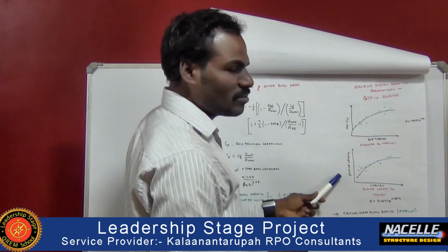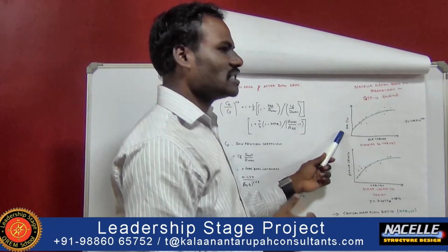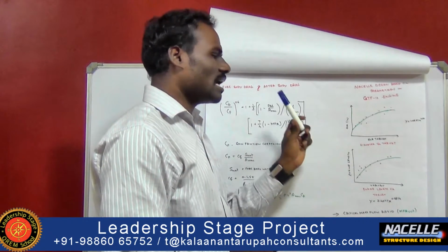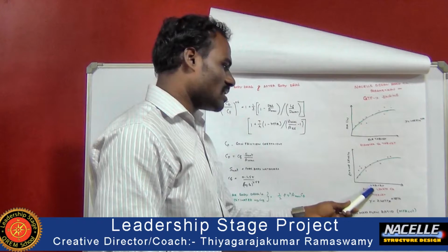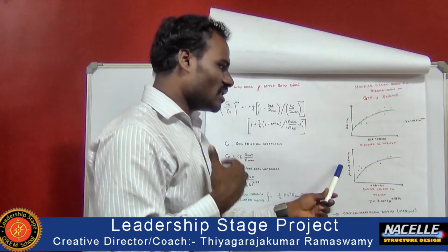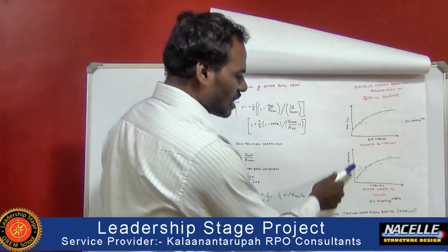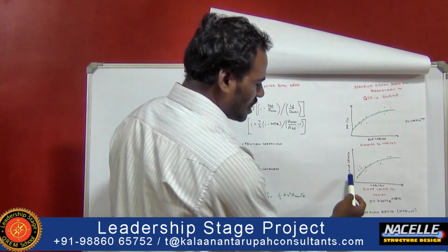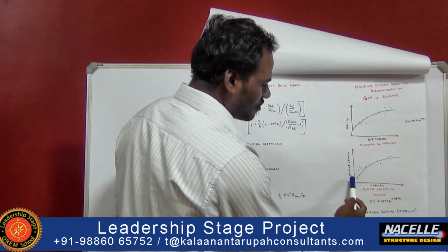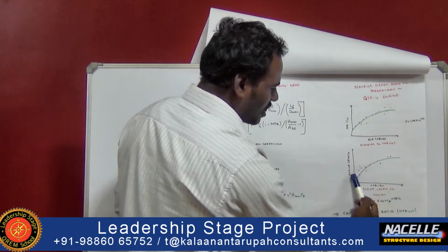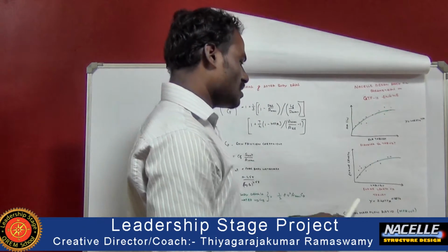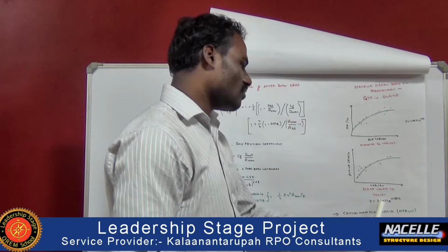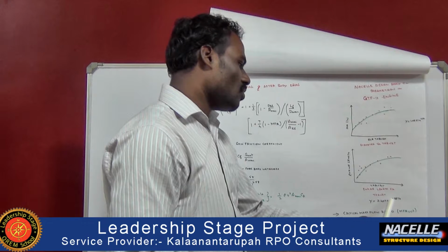These are both major values which we need to consider when designing a nacelle. With respect to the thrust value, the diameter of the nacelle is calculated. With respect to the thrust value only, the diameter and the length of the nacelle are also calculated. Here the graphical representation shows the nacelle length with respect to the thrust. This shows a better performance of the engine with y equal to 2.4077 x to the power